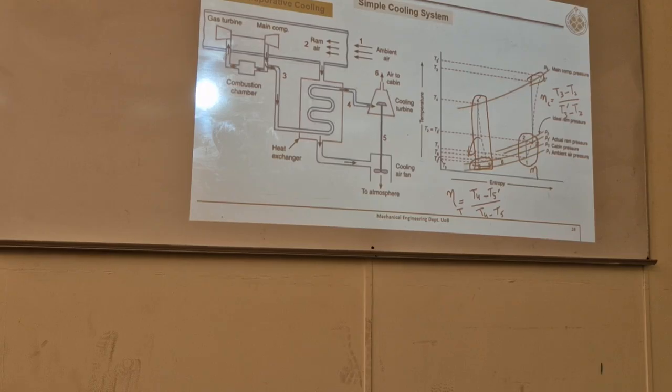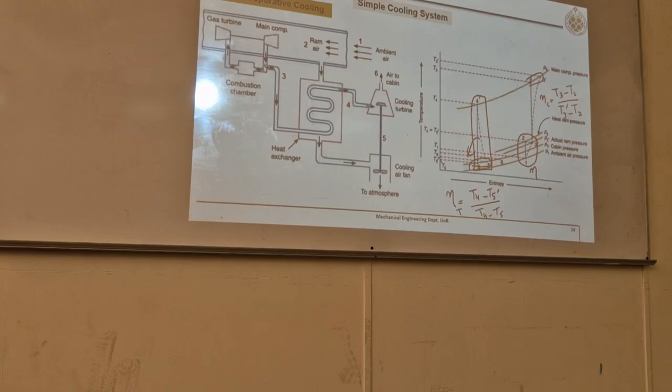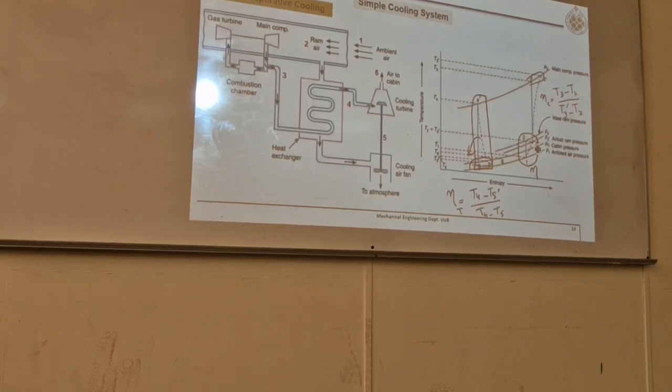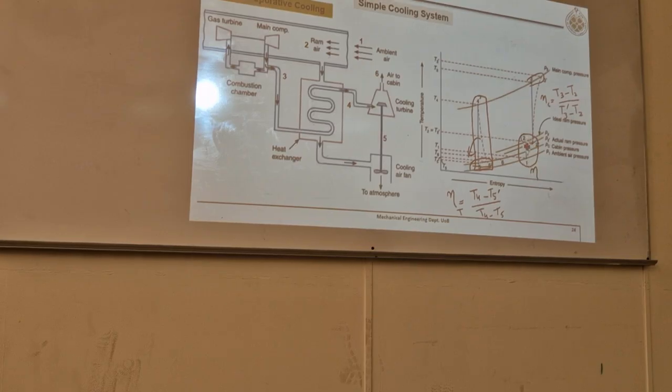Because what is a diffuser? Just a pipe and nothing else. So when the fluid is flowing through a pipe or a duct, due to friction, pressure drops. In the ideal diffuser, we said no frictional pressure drop. Okay, so that's why in an actual diffuser, the pressure will be lesser than the ideal one. So here pressure rises more, here pressure rises less.